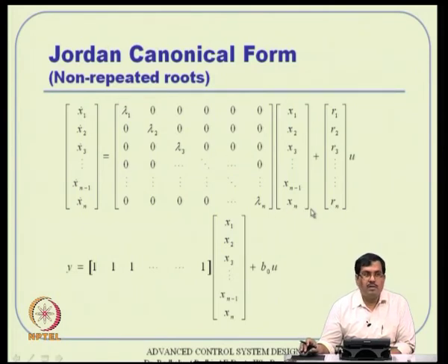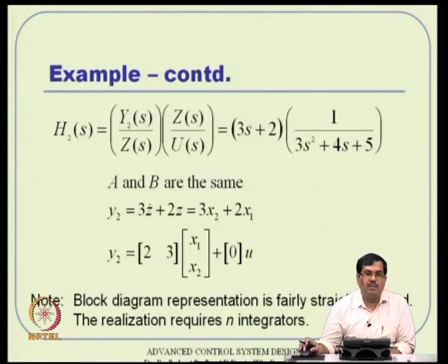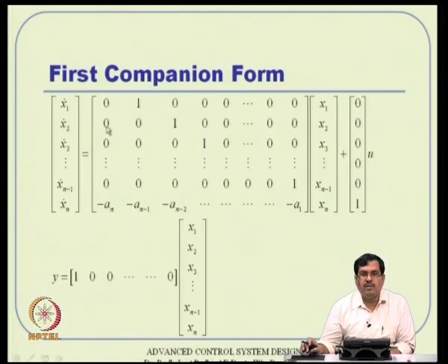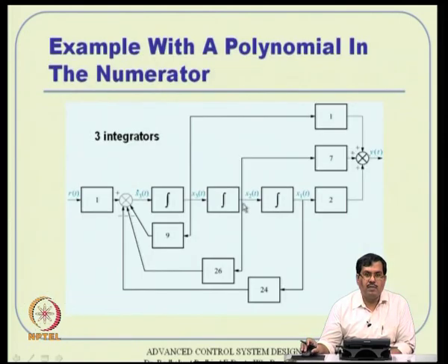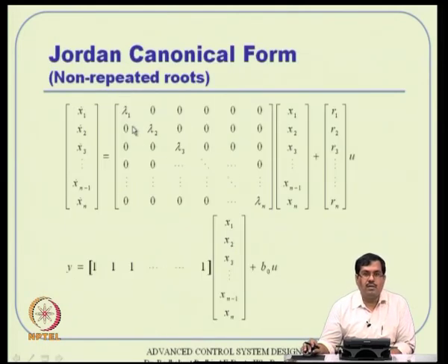Okay. So, suppose you started with this transfer function and went ahead and did that first canonical form, then the A matrix turned out to be different. I think we can see some of these examples also, if you go back there, the A matrix turns out to be that. So, certainly the eigenvalue information is not as clear as the other one. You really have to do the eigenvalue analysis on the characteristic polynomial to find out what the eigenvalues are in this form. But in that form it turns out to be very natural, it is just available for you. Okay, that's already there for you.